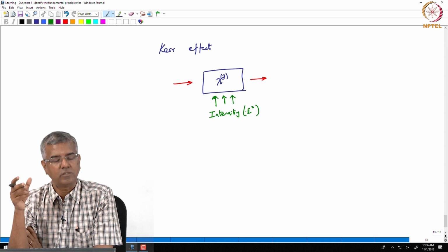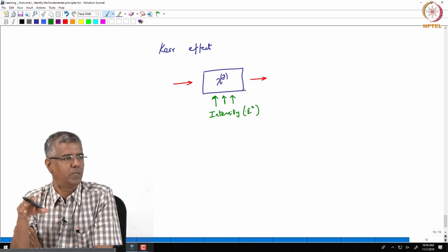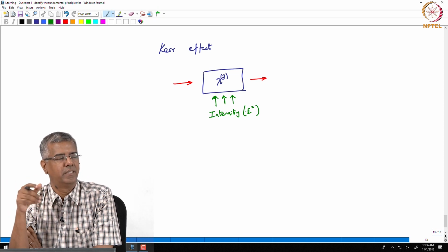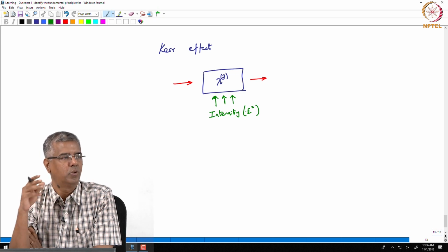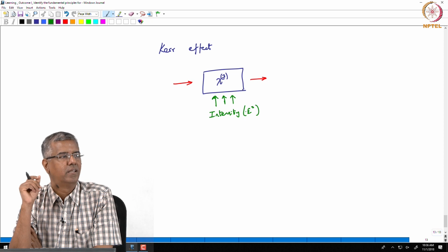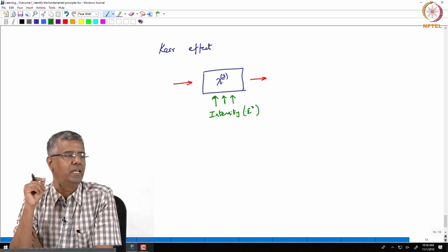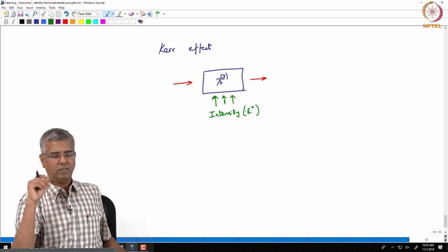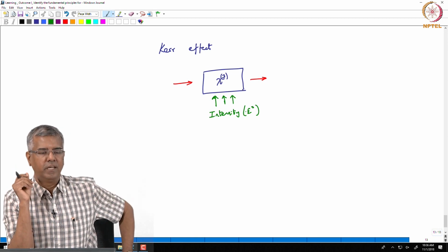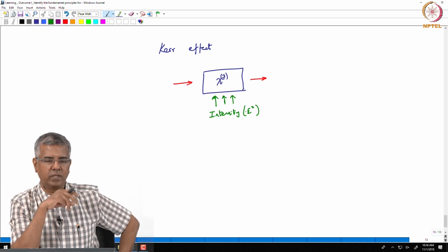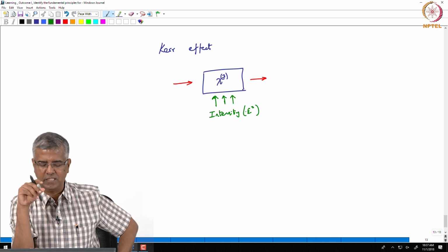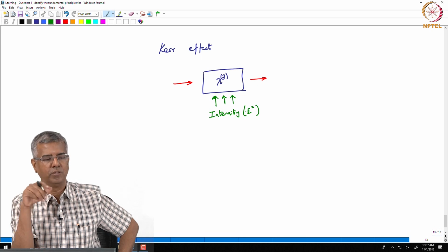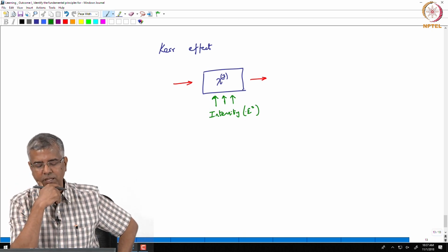Why? Because you have to apply your electric field through some electrodes, okay, and there is a finite time taken by the electrical wave to go across that material, and that would essentially limit the modulation frequency, okay. With a smart way of figuring out your electrodes, you go for what is called a travelling wave configuration, and you pattern your electrodes such that the field can propagate across at fairly high speeds.